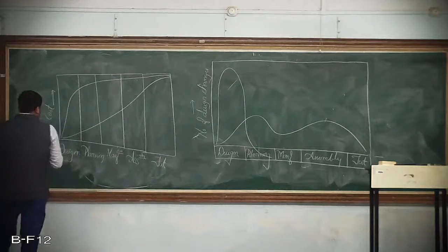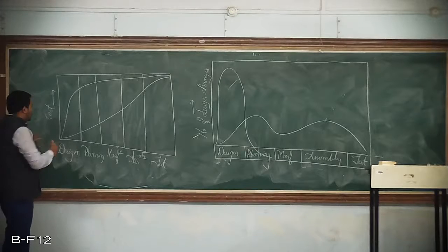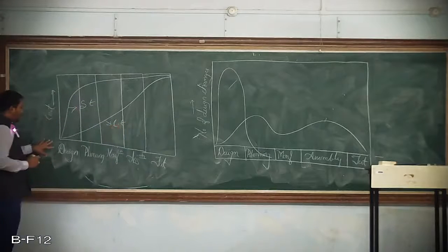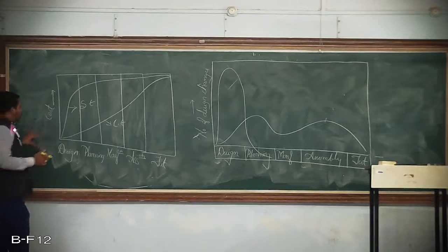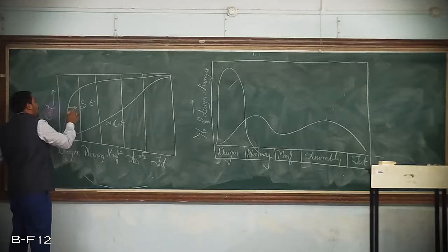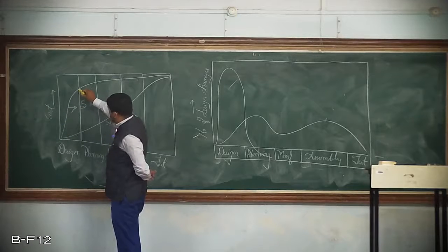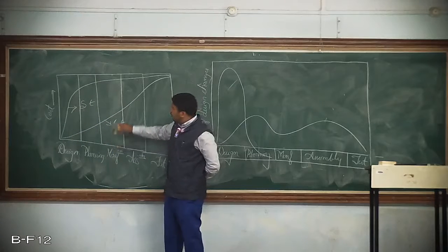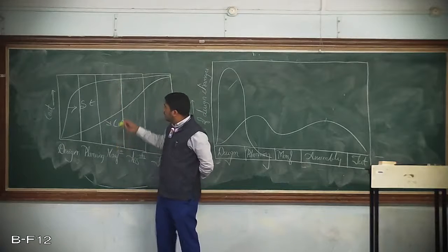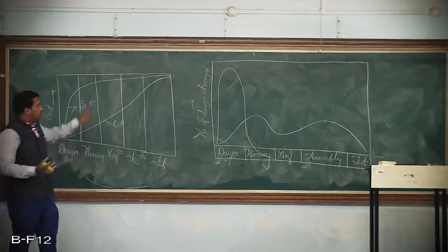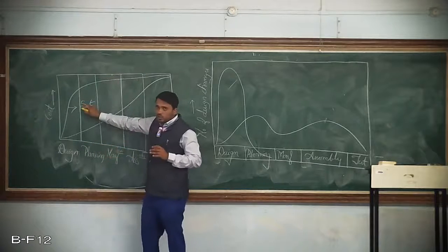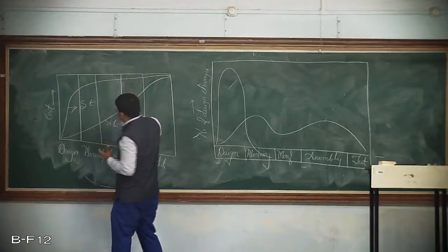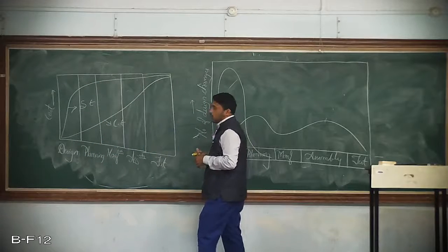Now, if you look at the cost associated with each of the phases in sequential engineering and in concurrent engineering, what you can notice is that because of continuous redesigns, the cost increases in the initial redesign, and again in planning, because frequent changes are taking place in the design as well as planning and also in manufacturing. If flaws are detected in manufacturing, that requires either scrap or rework. In sequential engineering that scrap or rework will be more because there will be a whole lot of design changes. Hence the cost associated with sequential engineering is always on the higher side across the different phases the product passes through.